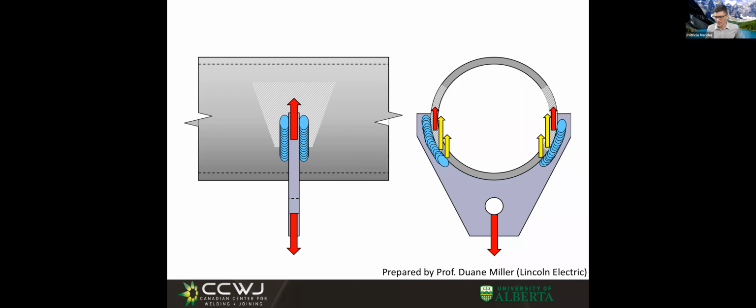Of course, we're going to see how we design for the size of this weld. But we should be aware, and for this, we do not have formulas. You can do finite elements, but really, do we need to? Because very often we can imagine all these things. In this weld here, the load is distributed with an emphasis on the vertical parts connected to the stiff sections, and with very little contribution of the center. When we design a weld, very often we assume that the weld is stressed uniformly on its length. Often that's true. It's not true in this case. So this is a better solution. Shorter welds, well designed, right? Cheaper, less material.